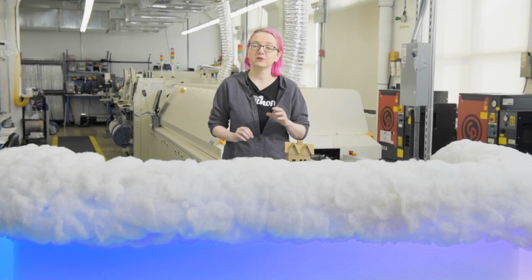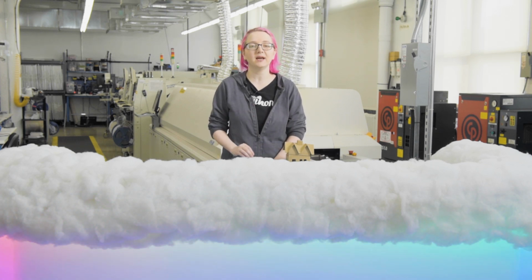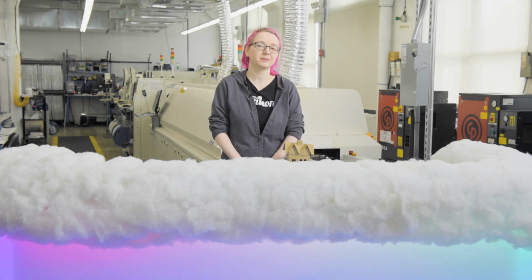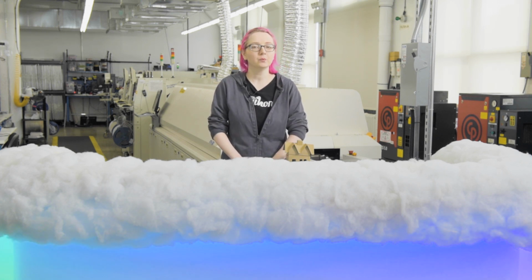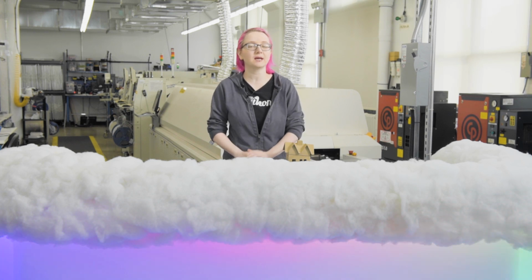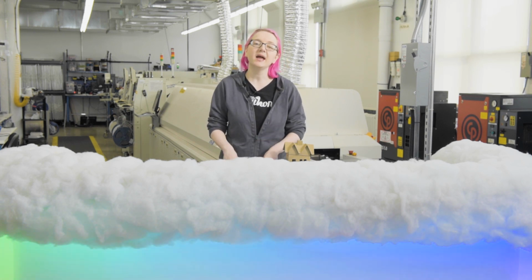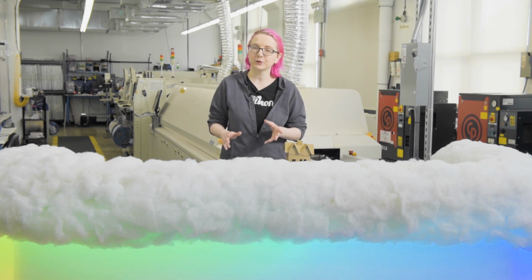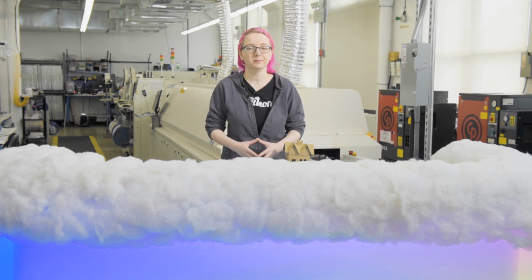We'll use the ESP32 as the microcontroller brains. It can use both secure Wi-Fi and Bluetooth LE as a transport, so you can make both internet-connected and mobile-connected applications. For inputs, we'll use the Analog Devices Featherwing to get precision temperature readings, and the Bosch BME 680 to get humidity, barometric pressure, and air quality input. We'll also add a magnetic door sensor to detect when somebody opens the door or window.